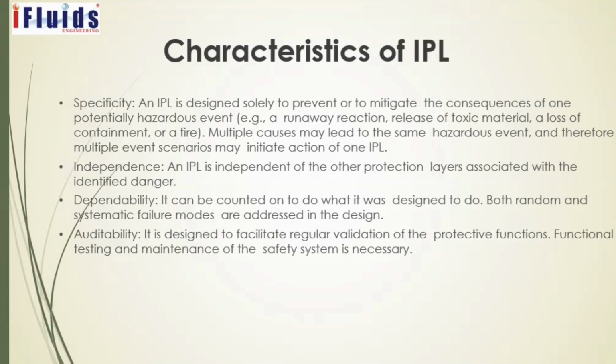Independence. An IPL is independent of other protection layers associated with the identified danger. Dependability. It can be counted on to do what it was designed to do. Both random and systematic failure modes are addressed in the design.